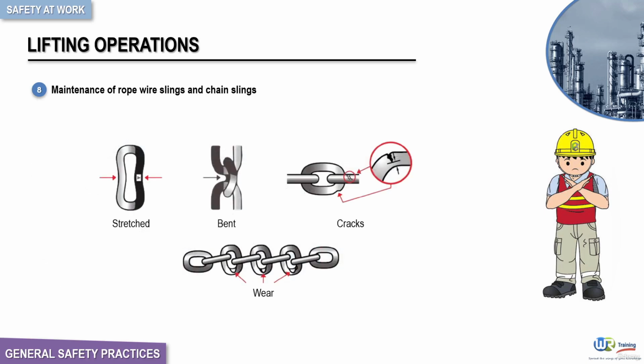The next figure depicts unsafe and unusable chain slings. Stretched, bent, cracked, or worn chain slings should never be used under any circumstances.